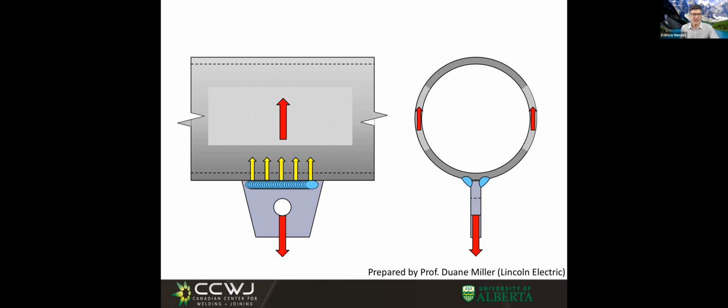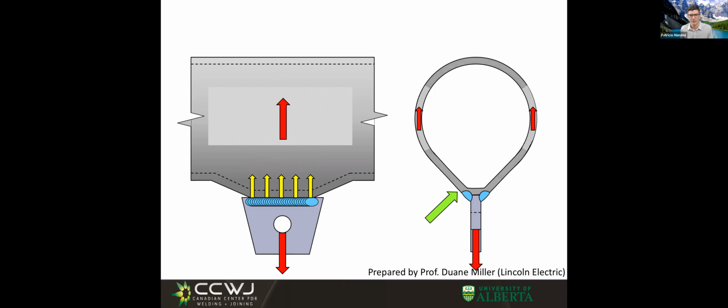And in this case, on the side view, I would be distributing it fairly uniformly. So I wouldn't be having a stress concentration lengthwise on the weld. But right here, check out what would be happening. Check out the toes, right? What you don't want is a tension in the toe, because a toe is a stress concentration point. Ha! What do you think of that? Of course, this is exaggerated.